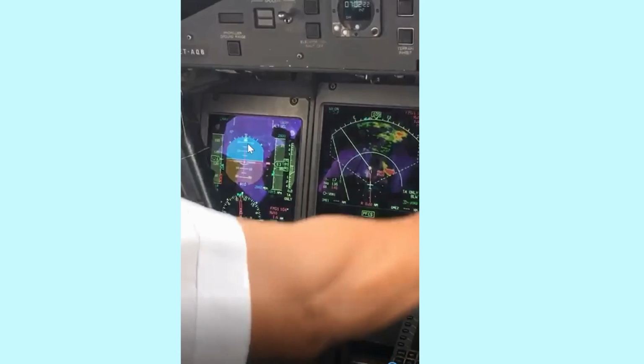Okay, on the Dash 8 PFD, the vertical speed indicator is here, as you can see. All right, and the vertical speed is indicated right at the bottom here in decimals. Now sometimes being humans, most of the time we cannot always glance at this little value here. It's a bit difficult sometimes, but I want you to actually see the wing bars. If you can see the black wing bars here, which are right now overlapped obviously by the flight directors, but the moment we remove the flight directors, you'll see the black wing bars here.